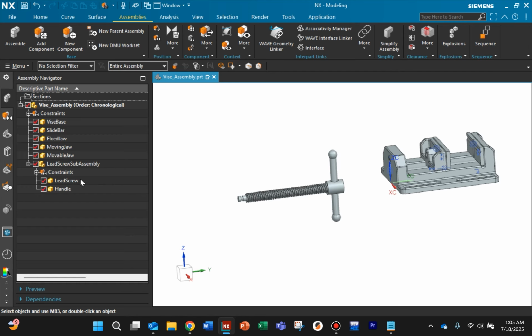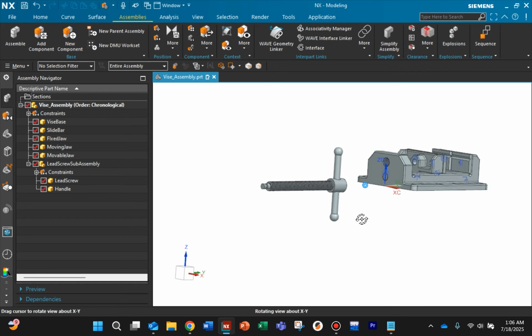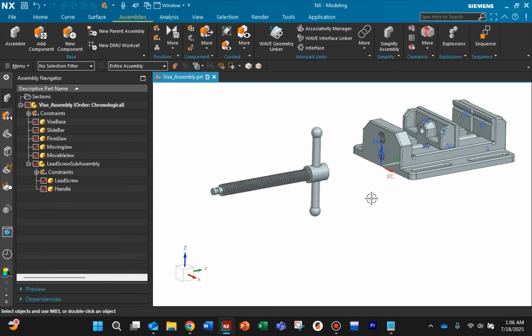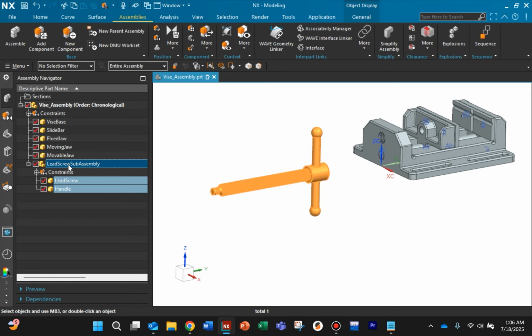So we can actually add assemblies to other assemblies. We call those sub-assemblies. This is a great way to break down components. If we think about the way that it would actually be assembled together, it might be assembled just like this, where this would be a sub-assembly component, which is then sent to the main line, making the actual Vise itself. This is nice because this is a whole separate assembly, so we could do a whole separate exploded view, a whole separate parts list, part numbers, all sorts of stuff just for this subassembly.